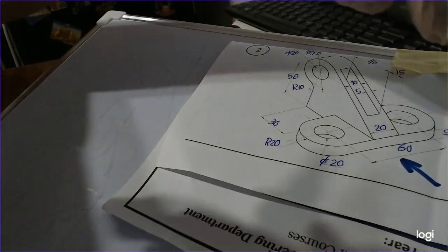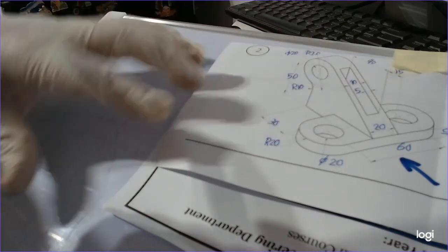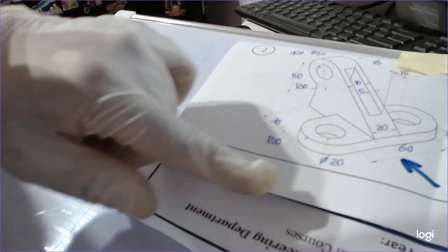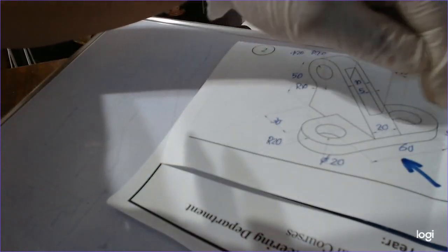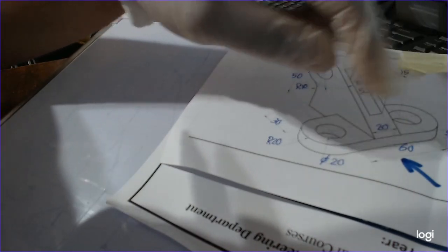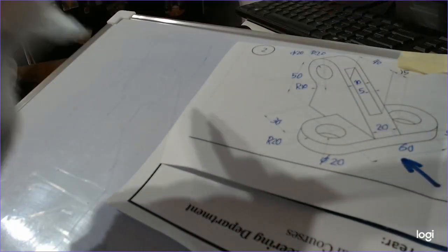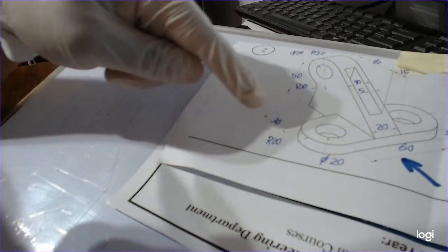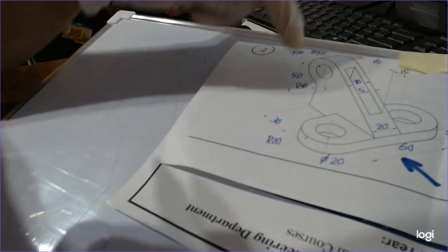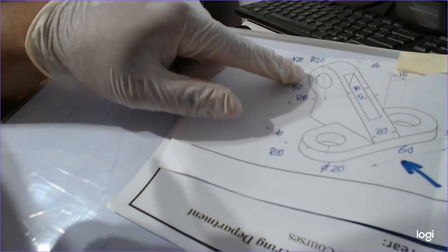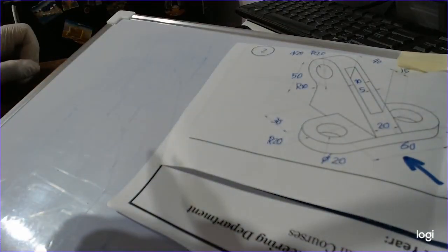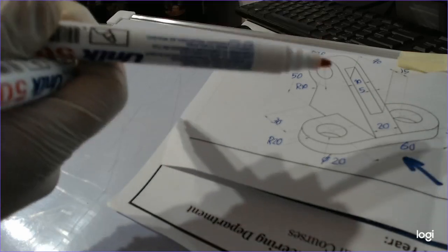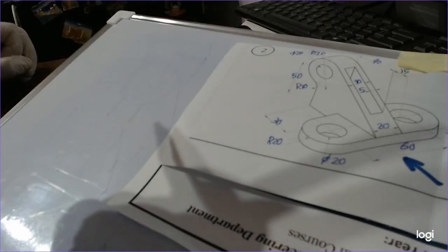So this view is actually 100, because we have 60 from those two center lines, and then we have an arc here with R20 and another same one here. So 20, 20, 40, and 60, so we have 100. And for the width, actually we have 40 here and 30. So this is 70, and then 20 millimeters from this center point to that peak point. So we have 90. So that means that this will be the largest view, the large open view, this one. Okay, so this will be the front view of our object.